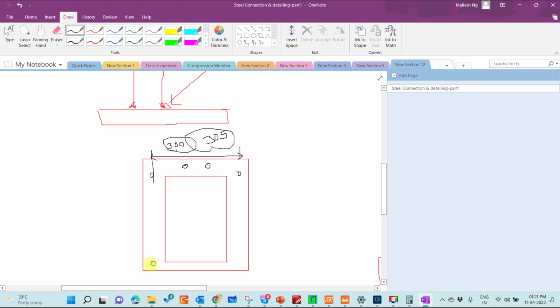So without knowing, we provided 5 extra, which is not as per standard. In those kinds of situations, you have to check and make sure that the bolt you're giving is within the range as prescribed in the particular code.